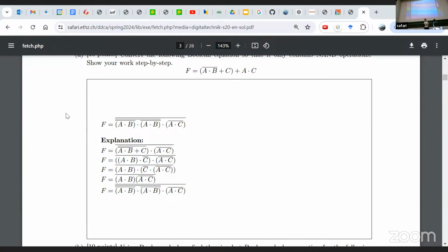Or they ask you something like, hey, draw the schematic, then give you the propagation delays, whatever. Would this circuit run at 1 gigahertz? Well, you have to put things together and then see if this circuit would complete in a nanosecond, the worst case propagation delay. Or they could ask something about the hold time and say, is there a problem here?